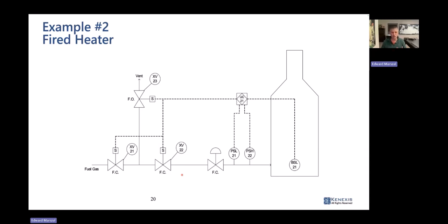If you haven't used the ISA and IEC rules and techniques, or if you're new to it, you might think that I have 2, either one of them will get me to a safe state, so it's a 2 out of 2. No. While it might appear arbitrary, and maybe it is arbitrary, what has been decided by the functional safety community is N is the total number of devices, and M is how many must activate to get to a safe state. And in this case, if either one of these 2 valves closes, you will get to a safe state.